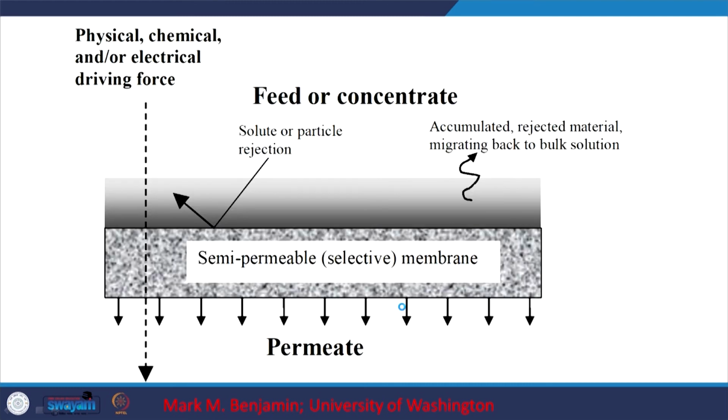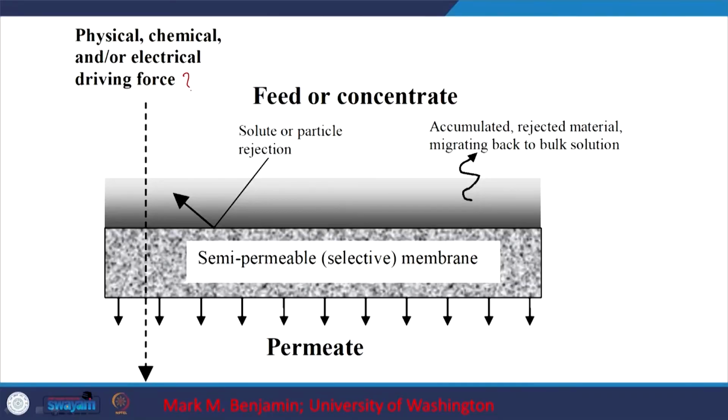But when we are talking about membranes, what is it that is going to drive this particular system or the water, and what happens here? For example, in depth filtration we had media of sand and we had water at considerable head. That head is driving the water through, and obviously you have head loss both due to the clean bed and also due to the ripening bed, and we looked at this aspect. So, here you are going to put in a driving force. What is the driving force? It can be physical, chemical or electrical, but here we are going to have pressure. The pressure is the driving force here, right.